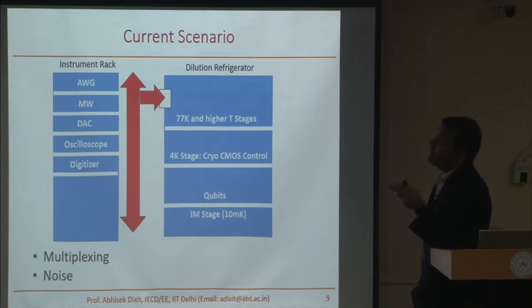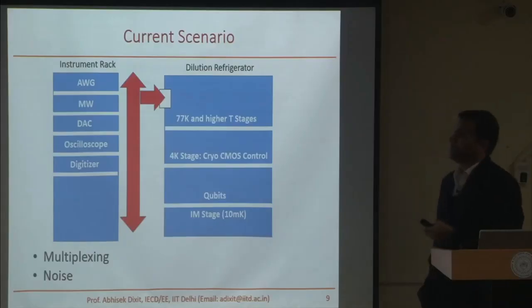Somebody actually pointed out how the traps can be so high. But experimentally we are back calculating and we are getting trap densities of that order. Maybe the back calculation procedure may not be correct. See, this is advanced research, so you have to look at all kinds of options. At what temperature is the capture lifetime getting longer, so that the traps are contributing to the capture?